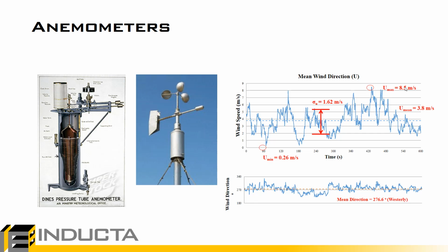So as structural engineers, we're interested in this peak value, this peak gust wind speed. What we mean by gust, it's not a constant wind speed, it's just basically a peak gust at an instant in time. So this is basically what is going to govern this ultimate design. It will generate the largest drag force on our structure.